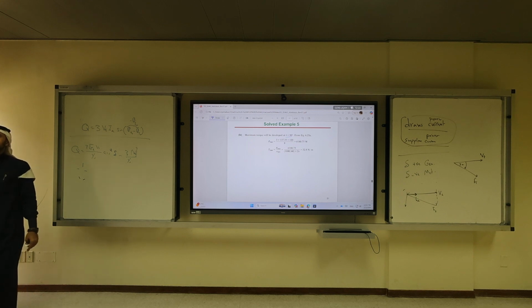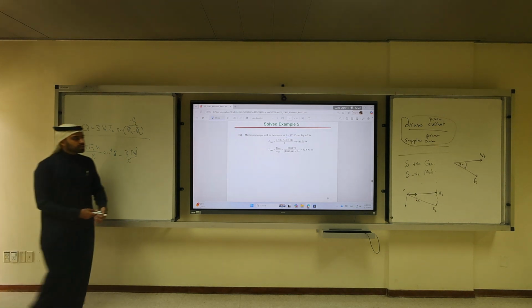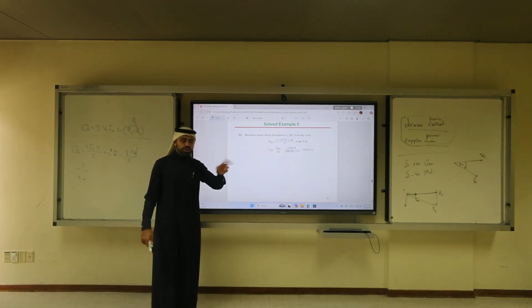I think some of them use another type of machine. It's called switched reluctance. In switched reluctance, the rotor is shaped as a triangle. This is another type of machine. It's synchronous, but it doesn't use permanent magnet or DC excitation. It uses another type of controlling the excitation. The reluctance would change.